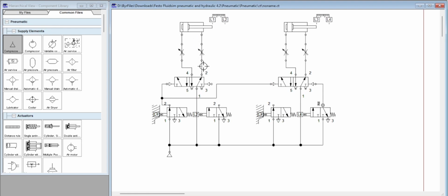However, L1 will also be pressing, so this cylinder 1.0 together with 2.0 will be extended together. But since L3 is pressed by 2.0 and it is being supplied here, this cylinder 1 will not extend because of the pressure here upon pressing L3 by 2.0.